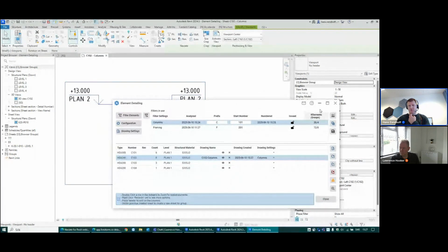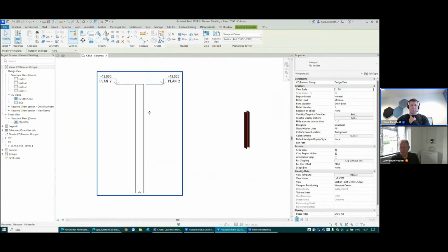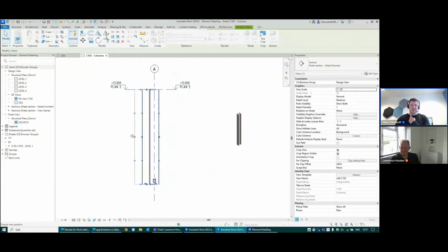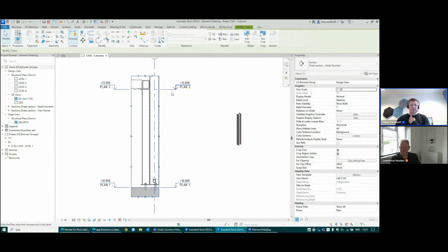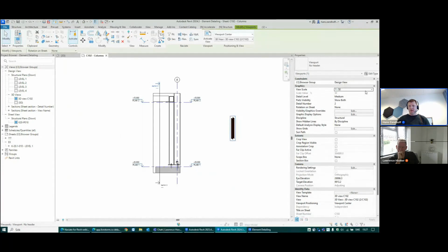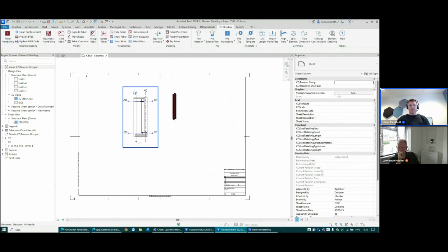section you used. So this section was 1 to 50. Maybe that's too small, so of course I can change that afterwards. We'll also always zoom in to the object, but if you want, you can go in and expand and see what's around this object instead, like this. And then you can continue to annotate and work with that element. So it's a way to quickly create drawings of all of the elements you have inside element detailing.